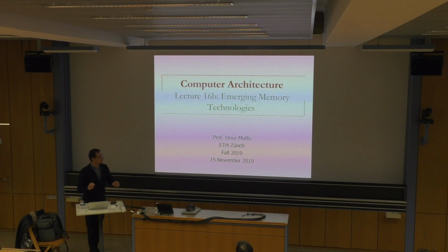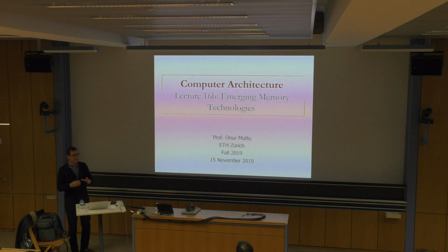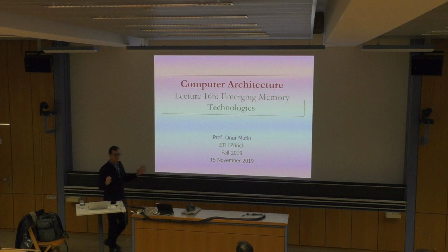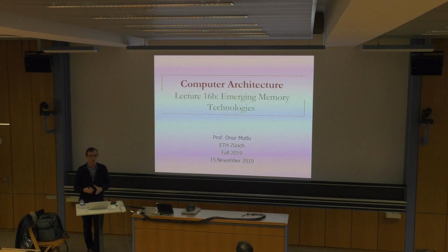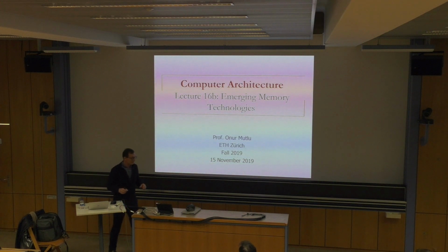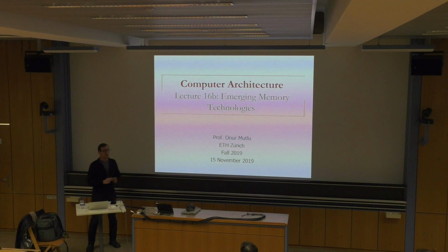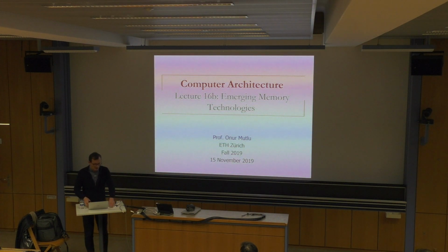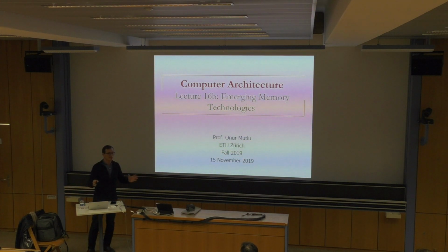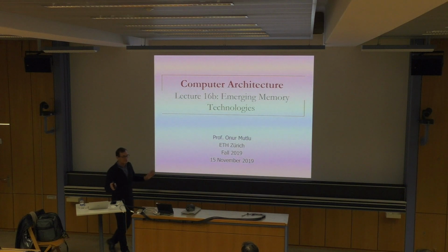And if you look at the broader space of memory technology, SRAM has been around for a long time, right? SRAM is a very powerful memory technology, very fast, unfortunately not very power efficient, and not very high density. As a result, it's not employed as part of main memory because of that. There are very few systems that employ SRAM as main memory. You can actually buy SRAM chips that you can attach to some processors. But that's not the common case, clearly, because you cannot afford a lot of SRAM. So if your data is relatively small, you can use SRAM as your main memory, but that's expensive.